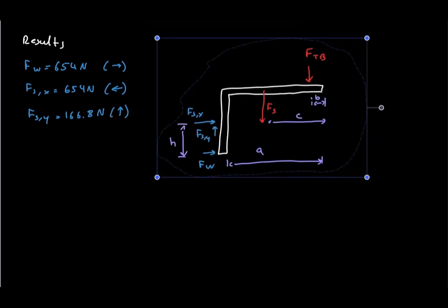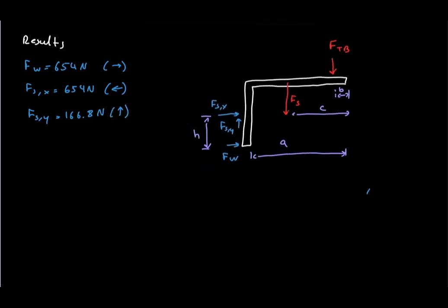The big lesson is that the toolbox weighs only about 147 Newton, but because of the moment arm, it creates a wall force of 654 Newton. That is why engineers do not only ask how heavy something is, they ask where is the moment?